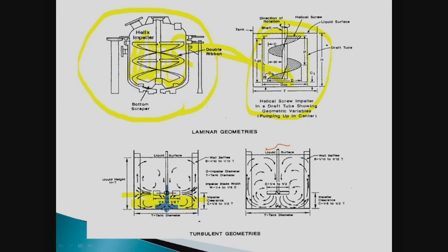I also perhaps would want to run a cone bottom, which may or may not be baffled. I suspect you really need to be baffled. And then I would run a tickler impeller all the way down into the cone. This way I could add different volumes in here. But I'm always looking for the fact that the liquid level can drop below the agitator and I lose mixing.